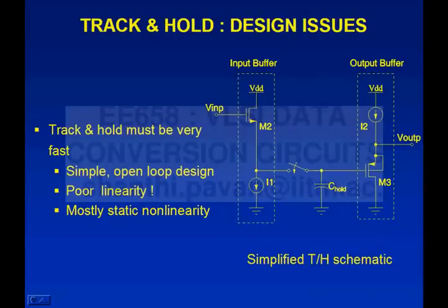You have more stages, right? With one stage you can't get too much gain. So you cascade many stages and attempt to get large loop gain, because that's when all the benefits of negative feedback become apparent. Which means that once you start cascading stages, bandwidth goes down, you need to compensate and all this other stuff, and you kill bandwidth, right?